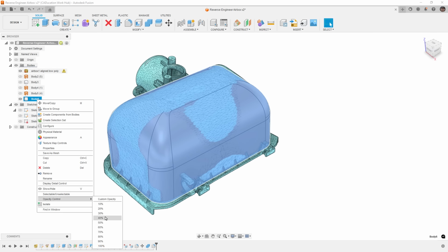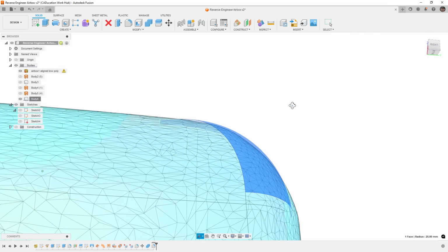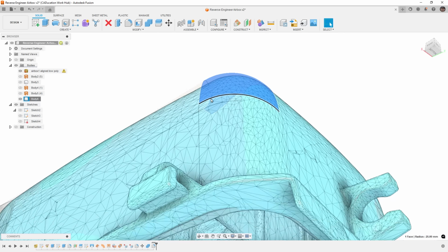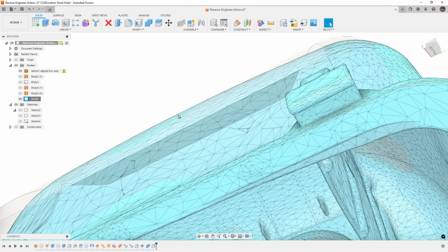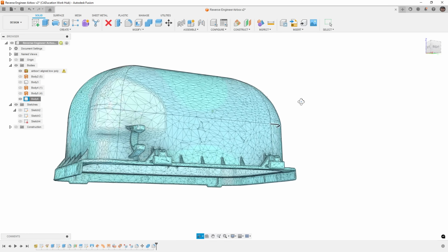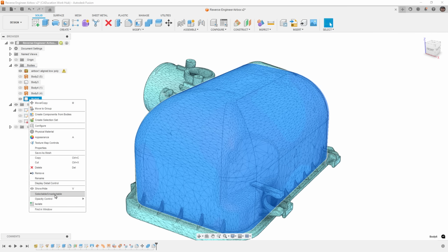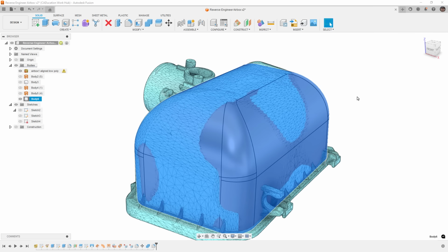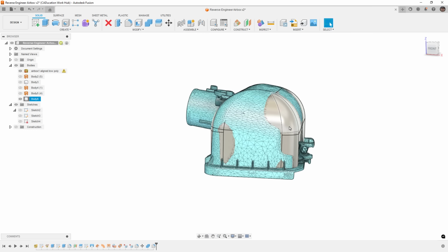If we go back to our opacity and we look, you can see that we're getting closer and closer to that fillet. It's not perfect, and it's never going to be with straight lines. It might be hard to tell, but you can see we're close in the middle, it overlaps, and then we get a little bit of a gap here. And that's simply because that back face is an arc and it's not a straight line. So there is not a situation where we're going to perfectly match with this method, because it is an injection molded part. Also, it's a part that was in use, so the chance of it being perfect, in original condition, is very slim.